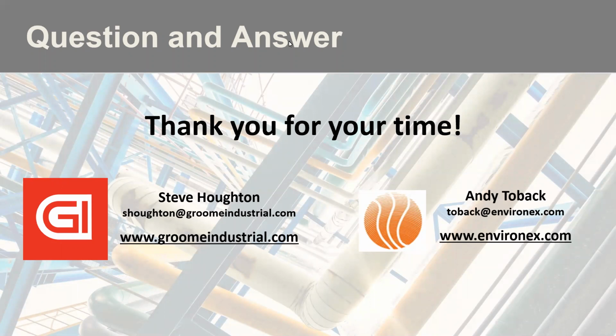That's the other benefit of ammonia tuning. So the less ammonia slip you have coming out of your SCR catalyst, the less ammonia is available to react with the sulfur in your exhaust stream to form ammonia sulfates. So that's the other benefit of ammonia injection grid tuning that is just a whole separate webinar that we could get into.